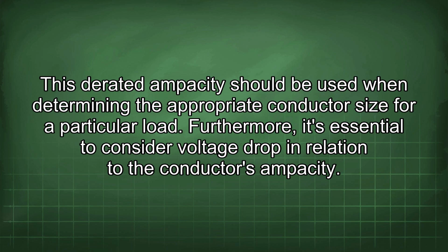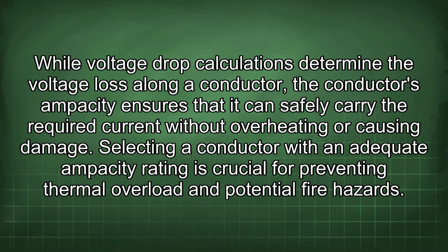Furthermore, it's essential to consider voltage drop in relation to the conductor's ampacity. While voltage drop calculations determine the voltage loss along a conductor, the conductor's ampacity ensures that it can safely carry the required current without overheating or causing damage. Selecting a conductor with an adequate ampacity rating is crucial for preventing thermal overload and potential fire hazards.